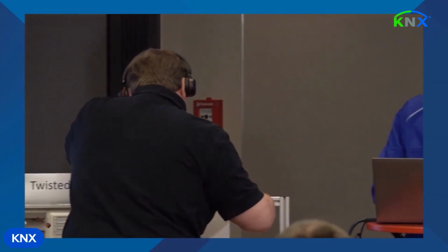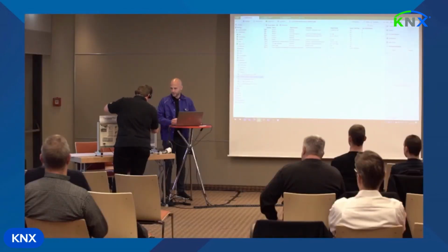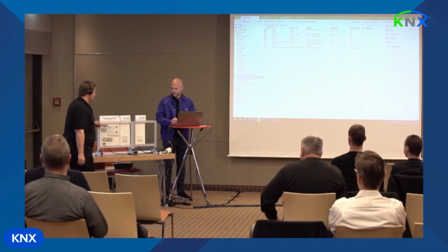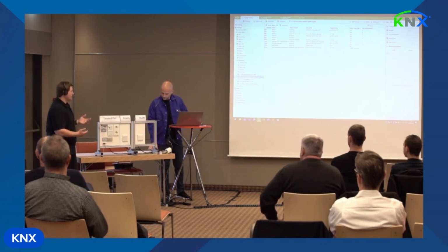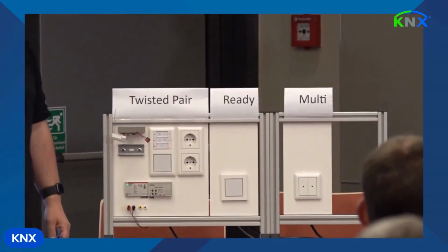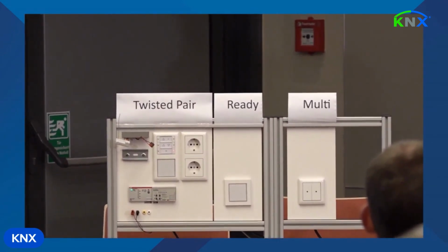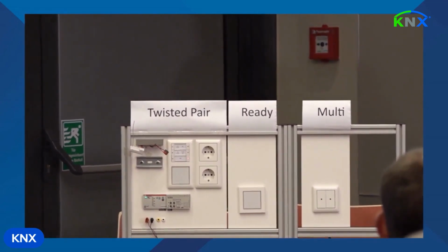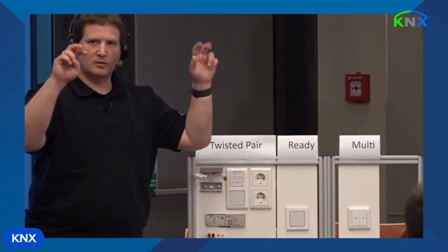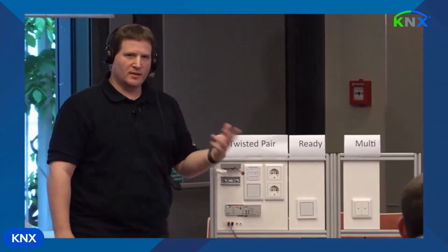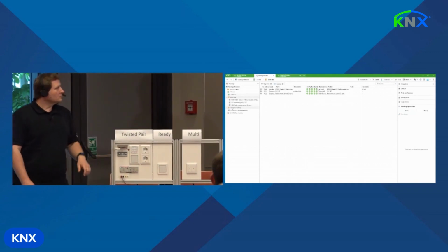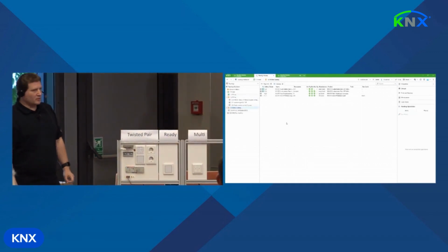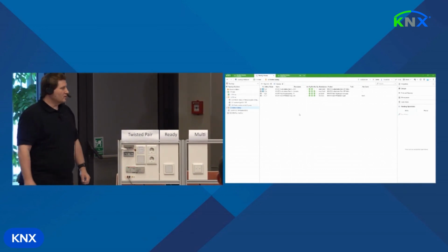Yes, we have now upgraded the installation. So this is the new KNX RF push button device, which supports the KNX RF Multi extensions. And the question is, does it seamlessly integrate into your existing installation? In ETS, you add this device from the online catalog. These are devices still under development, so they are not present in the online catalog. That's why we moved them into a line named online catalog in our installation, and from there we drag and drop it into our project.